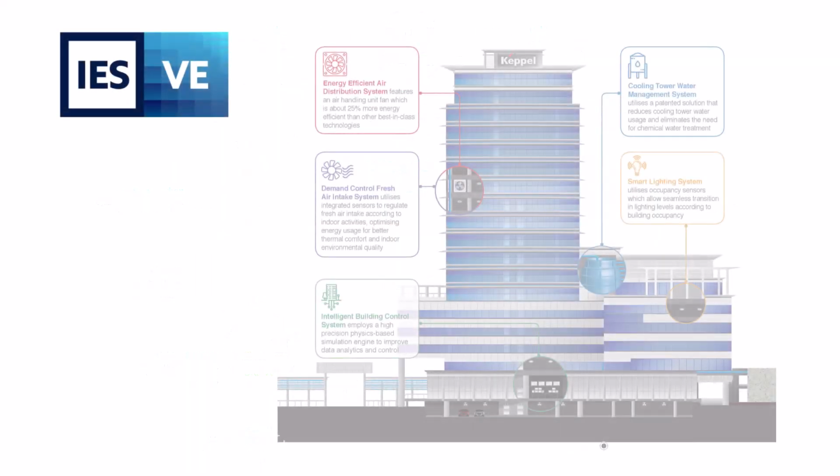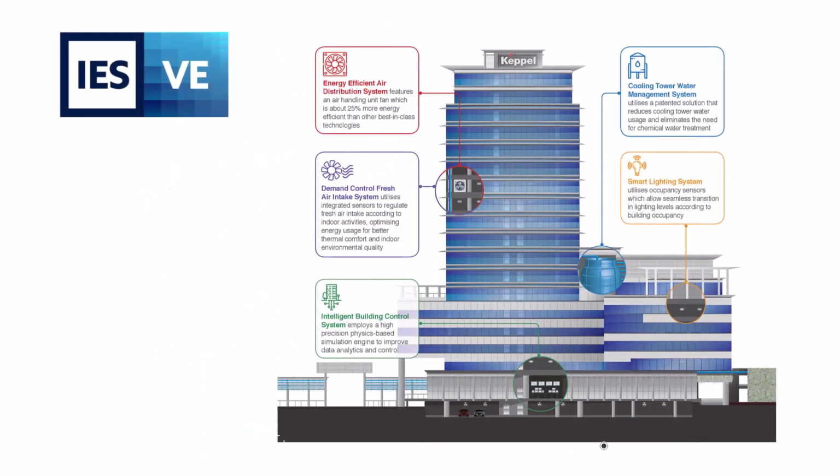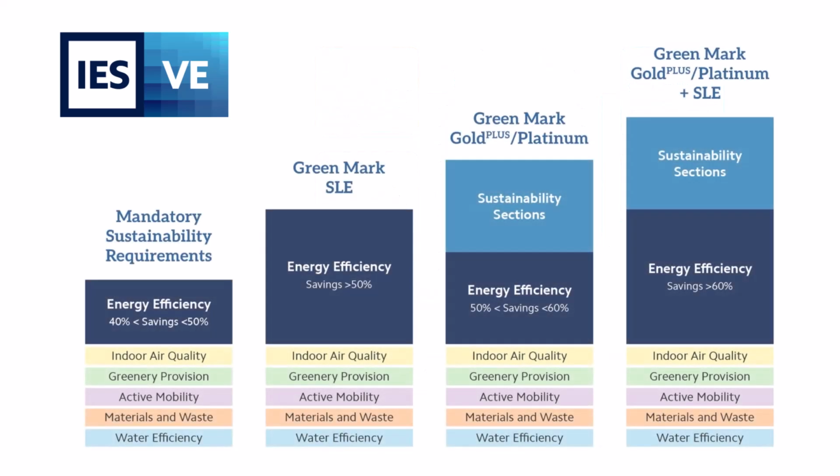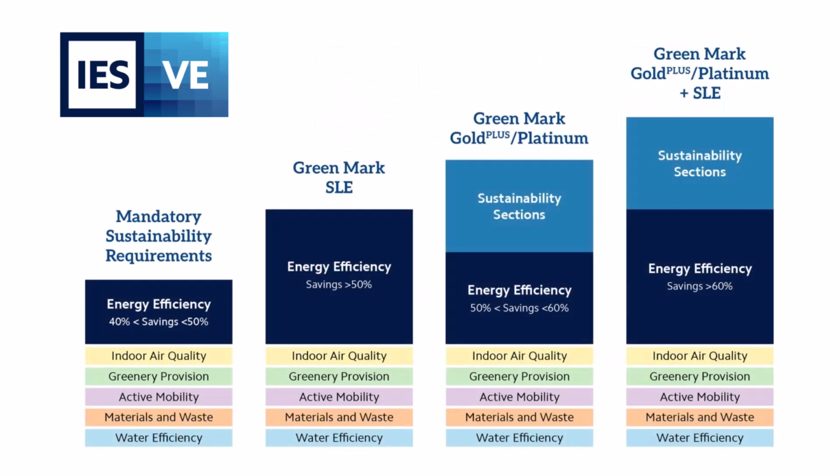The VE is an approved software for Singapore Green Mark compliance. It's capable of modeling the thermal performance of buildings in a multi-zone format. It can calculate the building's total energy consumption over a continuous 12-month period, and it offers more approved software solutions for compliance than any other vendor, including ASHRAE Standard 140, in line with BCA energy modeling requirements.